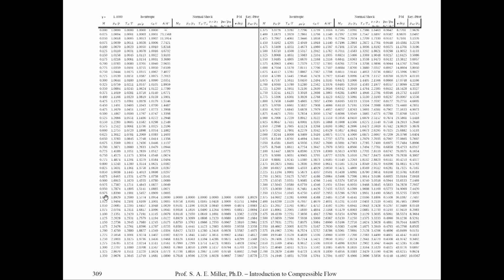And you can see there's Mach number 1 right here. So here's the transonic or critical condition. This is subsonic flow in the left, Mach 0 to 1, and the lower left from Mach 1 to 1.35. The table then continues on the right of the vertical line to M equals 1.3575, all the way to Mach 2.725. And then Mach numbers increase in increasing order on the following pages.